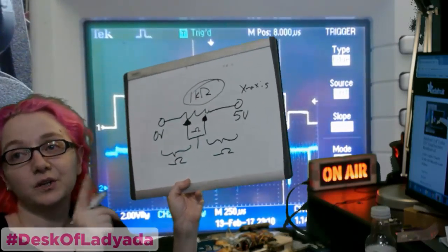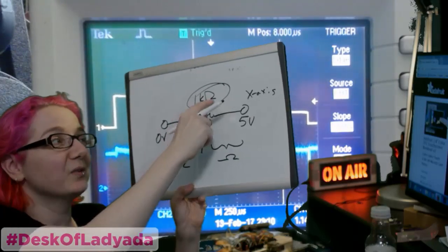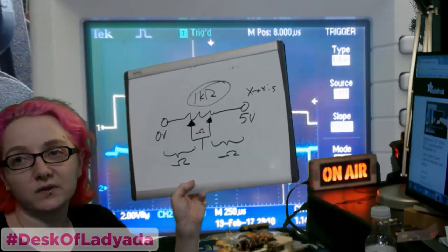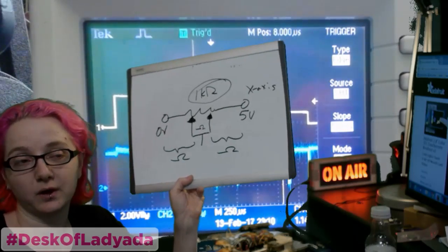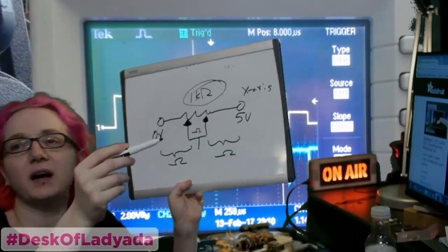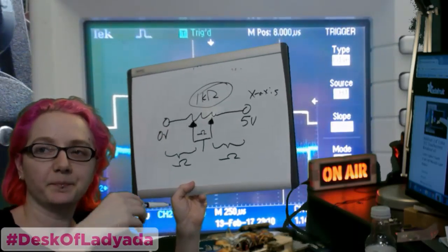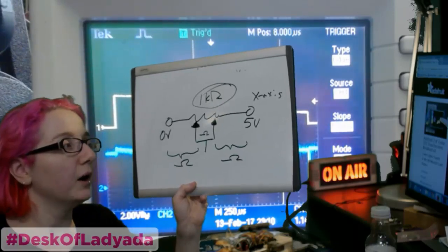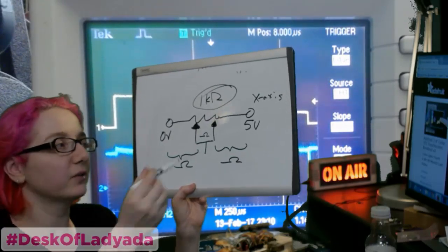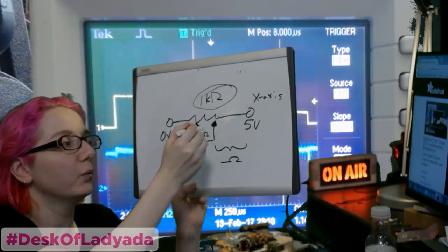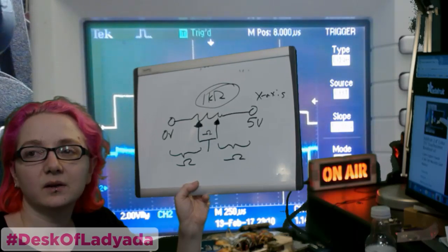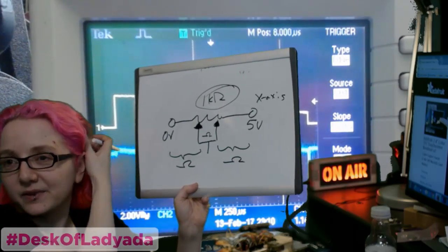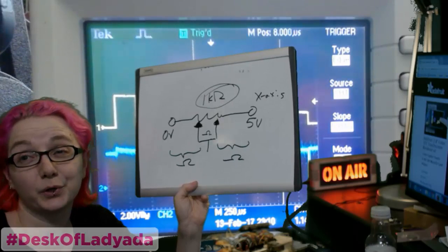And the thing is, there is variation from screen to screen. You can usually get specs for the resistance of your panel. Usually it's like 500 ohms to 1 kilo ohm resistance from point to point, but it's not guaranteed. It can vary. And so if you try to do 2-point touch with this technique, you'll have frustration because it'll be imprecise. You'd have to do some serious calibration per screen, whereas with single touch, you can kind of get away with not calibrating per screen.